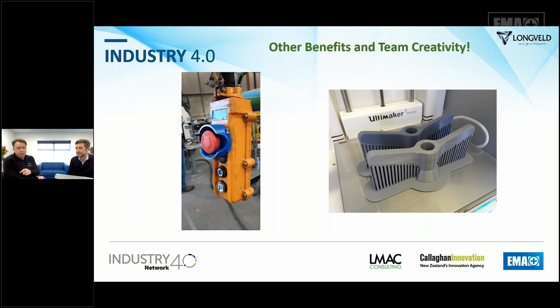The current design of those wing nuts is made by 3 parts, so it's a lot of labor consuming. They have to CNC machine the boss, weld the 2 rods, and then polish. So sending that for casting, they can just cast with the machine here with the mill, and then insert the boss. So that allows us to not use labor for this type of component. It's basically a similar cost, but we can use our labor to actually put a tank together, not making components.